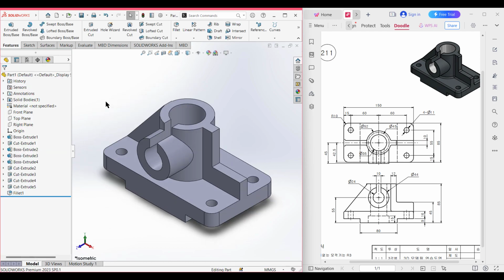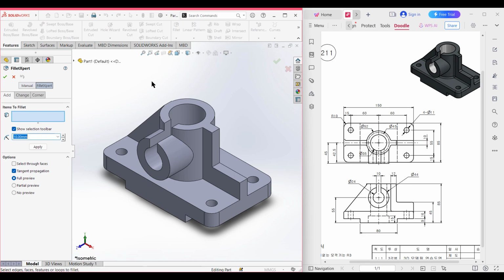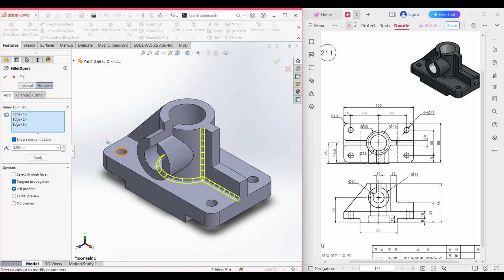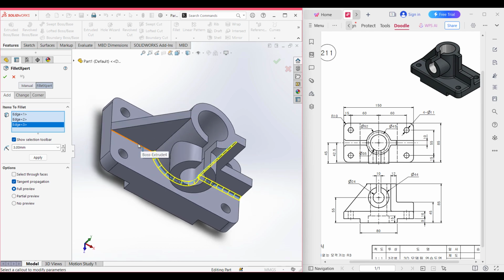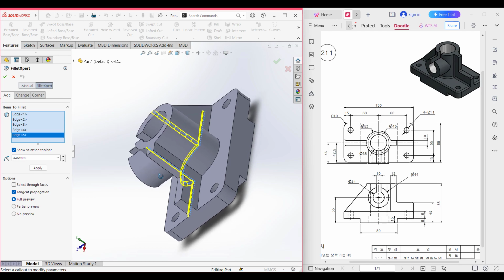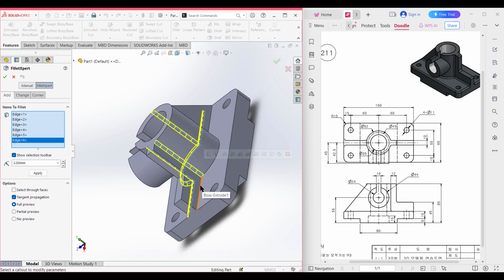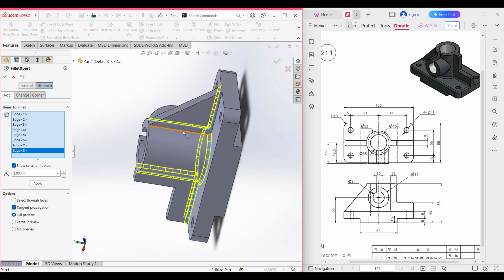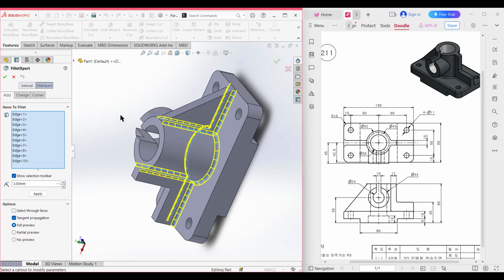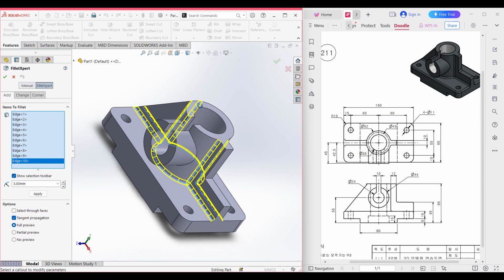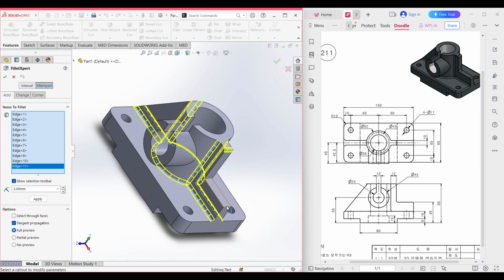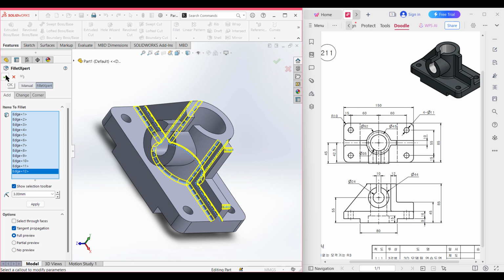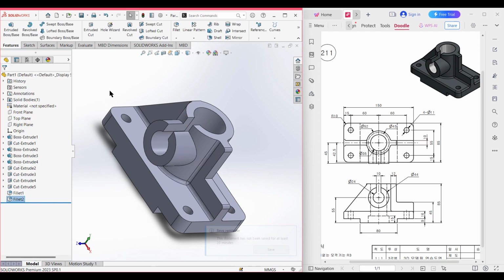Now the smaller fillets are the 3 unit fillets. For that I'm selecting the fillet option, and this is a fillet of 3 unit. Okay, so I'm selecting this line and select this other line also. Rotate here and select these points. Okay, now again rotate your sketch and select the other side also, the same fillet option. Now press OK. So our fillet portion has been done.